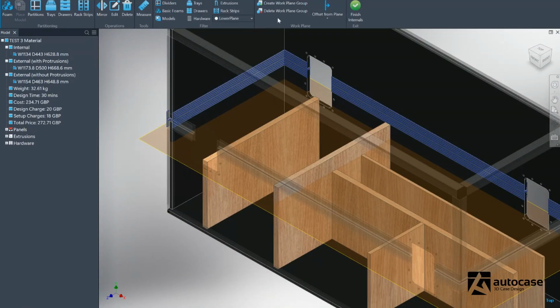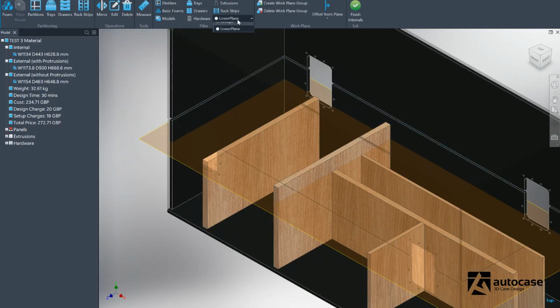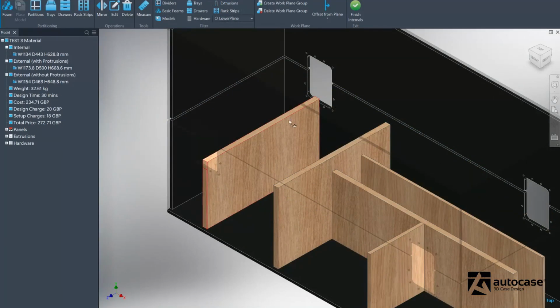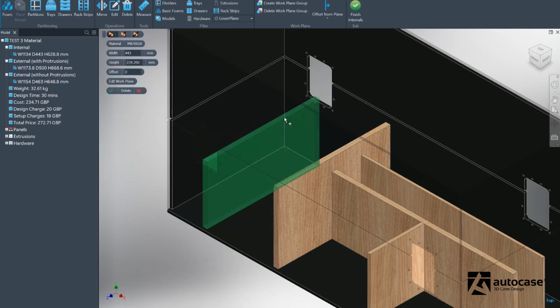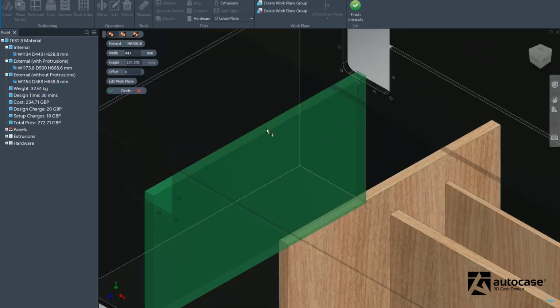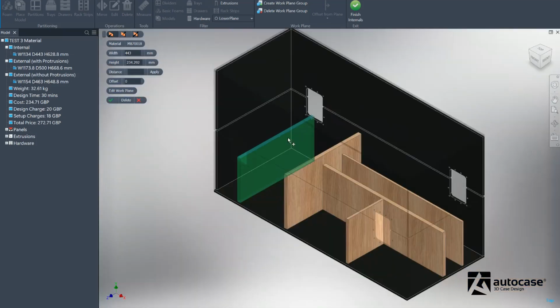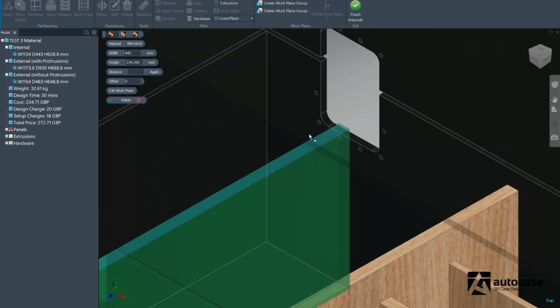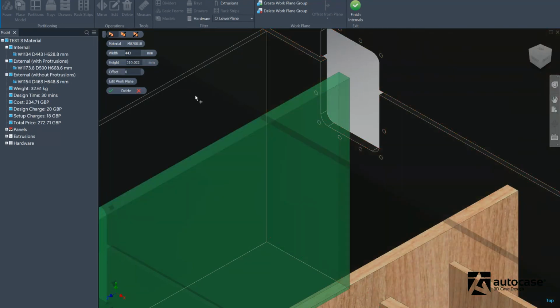So what we would do is remove the extrusion from the visibility. We can also remove this work plane. We're going to edit. I'm going to click on the first partition, and you hover over the edge, the face, and you'll see it highlight. Click on it and it will go blue. At this point, it's waiting for us to re-reference. I'm now going to select this face and now go to my green tick.